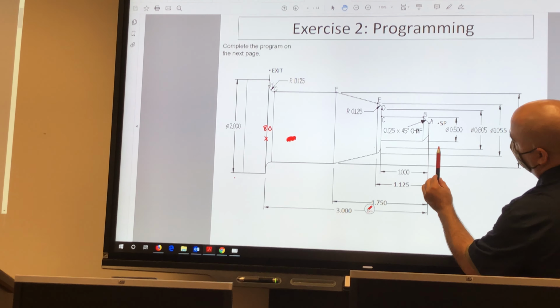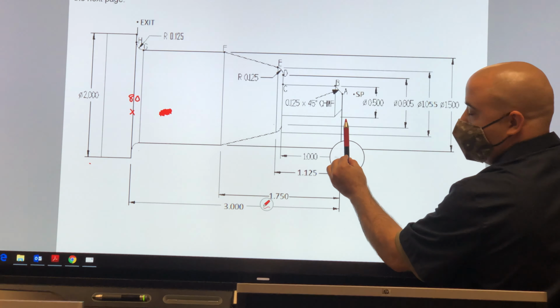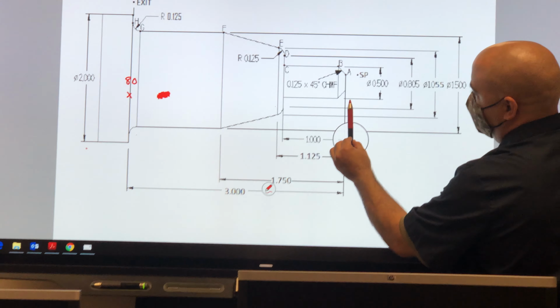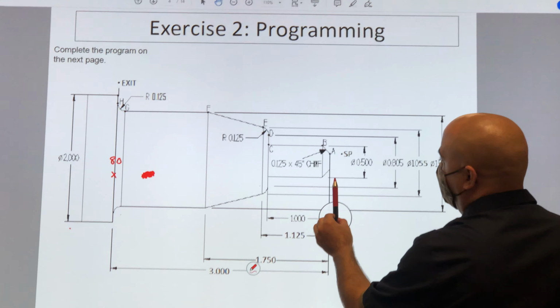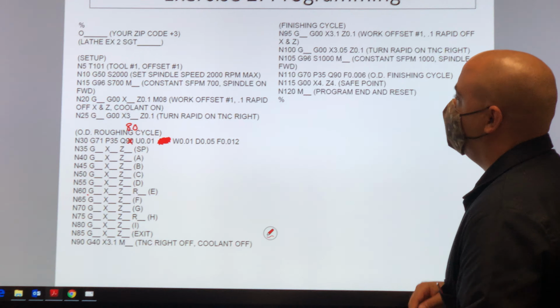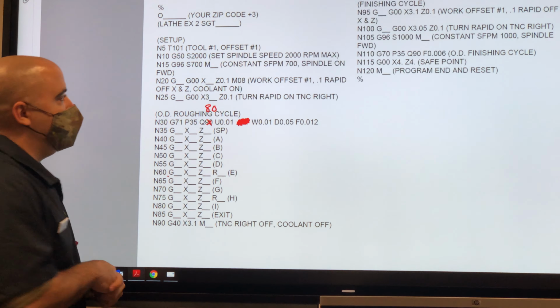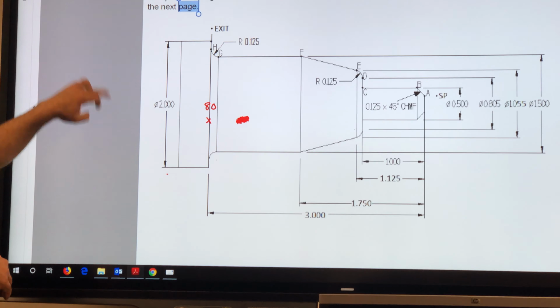So you're saying in theory it should come to right here? The Z is basically where your start point is. So you can start your machine, it can get running, and you can see approximately where it's going to go in at. And then you would move on to your M08, which is your turn on coolant, so that you don't burn out the cutting bits.